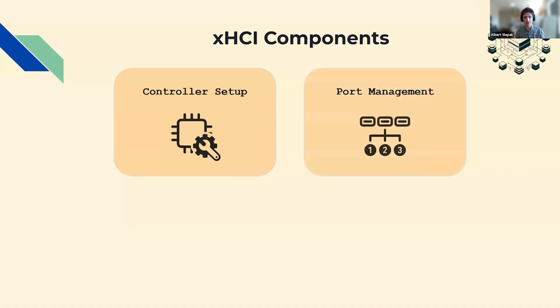After that is done, there is the port management aspect. In this series, we'll talk about how to go from the physical ports in your computer or laptop, where you can plug in USB devices, to how they are represented in the xHCI controller's world, and then how to also abstract them into the kernel's driver, and how to represent that in software. Additionally, with port management, you can either take away or provide power to the ports, so you can enable or disable them based on your power consumption requirements, and you can detect connected devices.